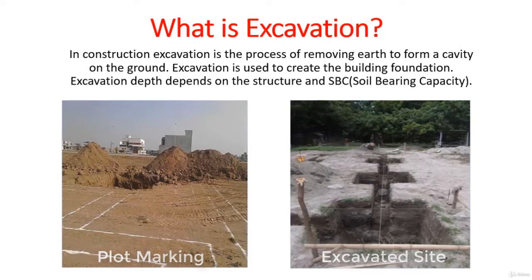The depth of the excavation depends on the structure and purpose of the building, like commercial, residential, and the number of stories in the building. Also, one more important factor is the SBC, soil bearing capacity, where we find out the soil bearing capacity of the soil in the foundation area.